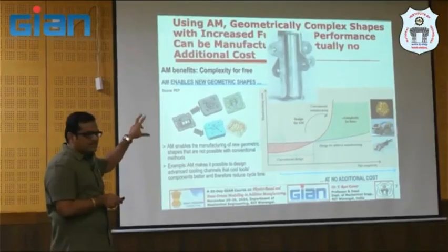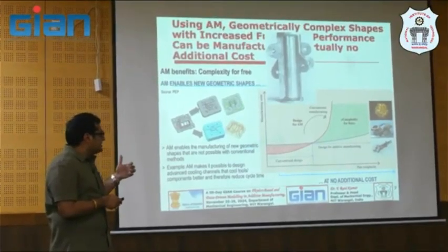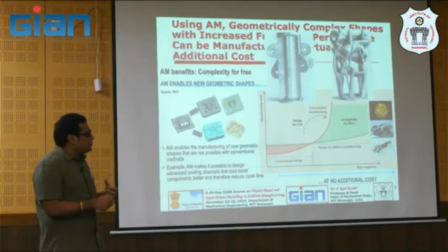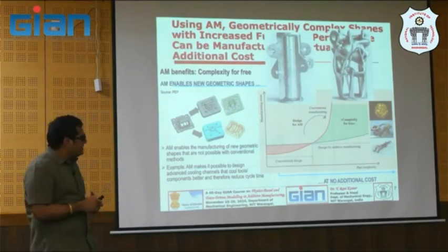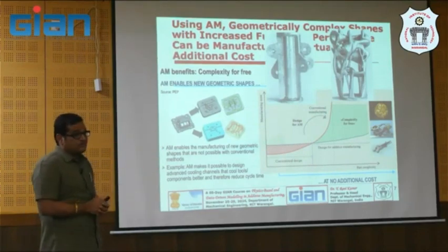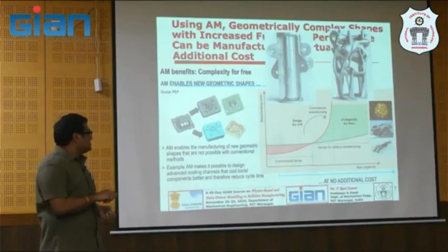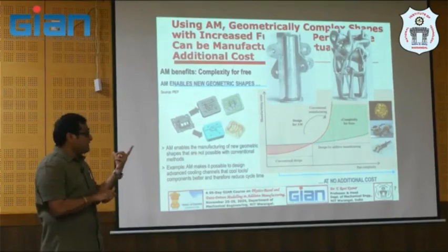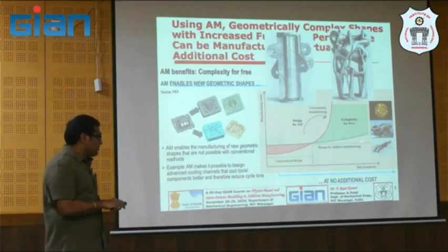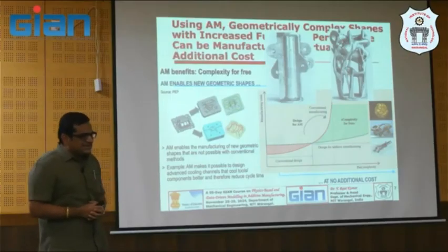Always you have circular, cylindrical kind of features, but your designer has changed this design to a bio-inspired or to a topology optimized structure, right? So your complexity, if you see this is 1x complex, it may be 5x or 6x complex. So then your cost is also now, it may be 5x or it may be 10x if you manufacture through a conventional method, right? But additive is a guy which always remains constant, right? So irrespective of your complexity, your cost remains the same. That's what this guy is the winner here.